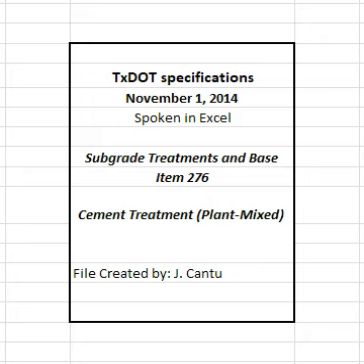Shape and maintain the course and surface in conformity with the typical sections, lines, and grades shown on the plans or as directed. Trim grade deviations greater than 1/4 inch in 16 feet measured longitudinally or greater than 1/4 inch over the entire width of the cross-section in areas where surfacing is to be placed. Remove excess material, reshape, and then roll with a pneumatic tire roller. Correct as directed if material is more than 1/4 inch low. Do not surface patch.